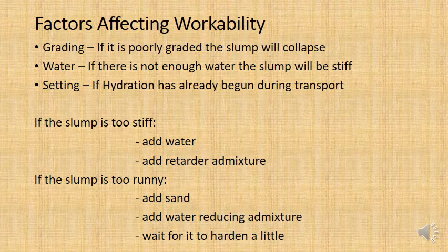But the other factor which affects workability is the process of setting. Now remember what I said, the hydration reaction between cement and water starts very quickly with Portland cement. And so it will begin to set, it will slowly go stiff even after you first mixed it.